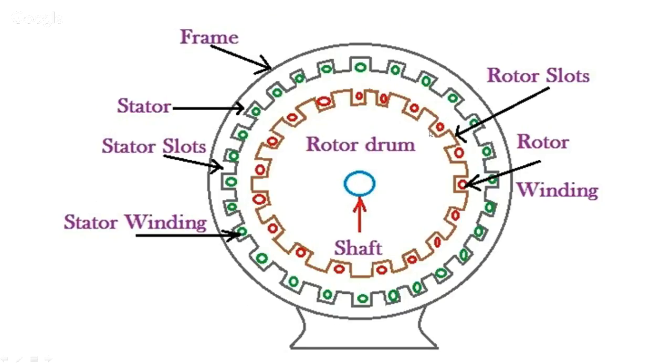And when this rotating magnetic field cuts across the rotor windings, it will cause a torque. Torque is a twisting moment or a rotating force. Therefore, some of the conductors will be pulled downwards, while the other half of the conductors will be pulled upwards.